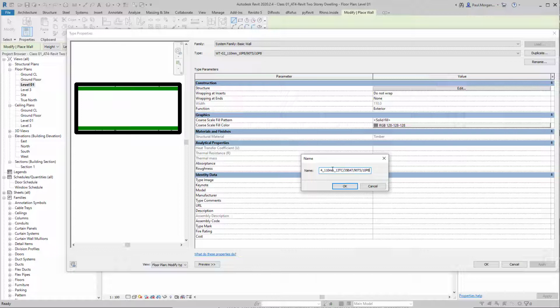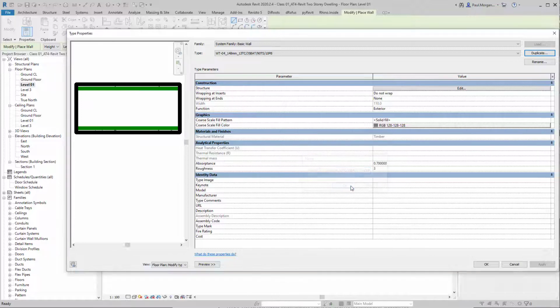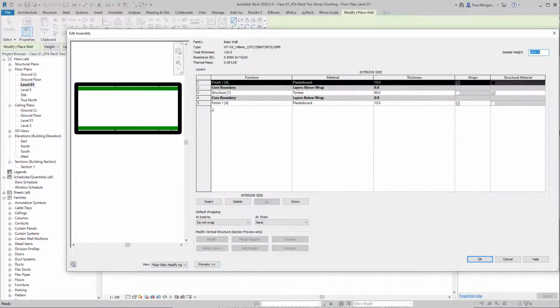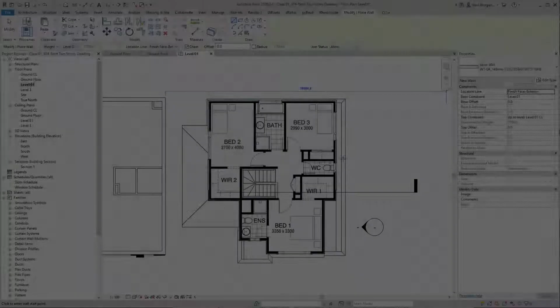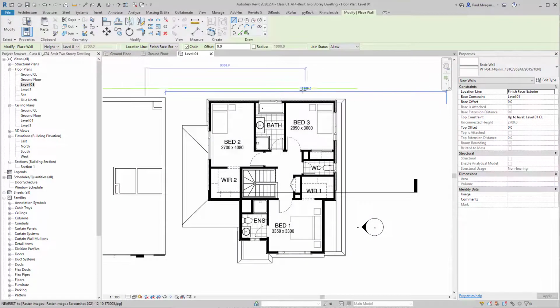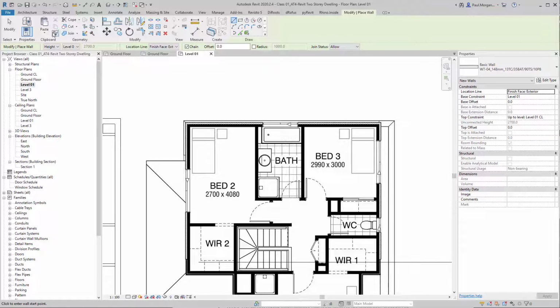So our total thickness will be 148 for this wall. Okay, that's now done. And now I'll just add this again, so not much to change there. I can do this quickly. So again, just checking our properties before we start drawing the wall. We're going to go with height. The height will be up to level 1 ceiling, at least at the moment.